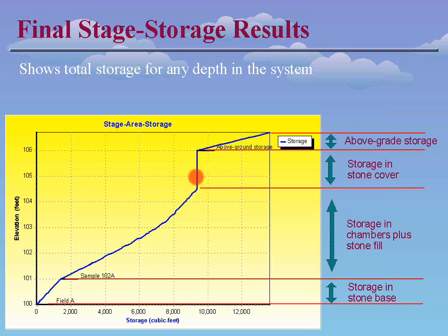We may have an impervious layer on top of the chambers. And then we might actually have some additional storage above grade. So if this storage chamber system is underneath a parking lot, then when the chambers fill and the connecting catch basin fills up, we may actually start storing water in the parking lot above the system, perhaps in the 100-year event. So all of that information is combined by HydroCAD in order to create the overall stage storage curve for that pond.